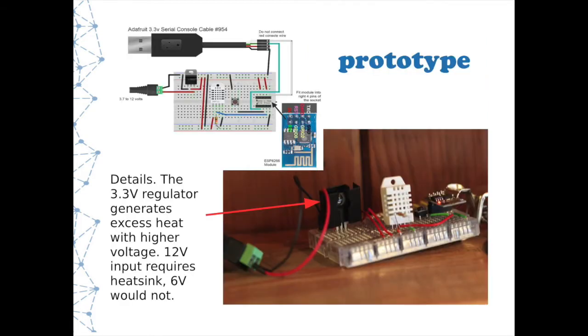So I built a prototype. And again, in the details, I'll make a note about a simple thing like voltage regulation. This thing works at 3.3 volts, so whatever your input voltage is, like if it's 12 volts or 6 volts, you have to regulate it down to 3.3.